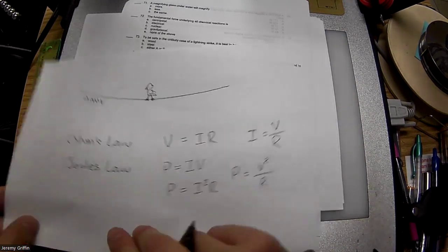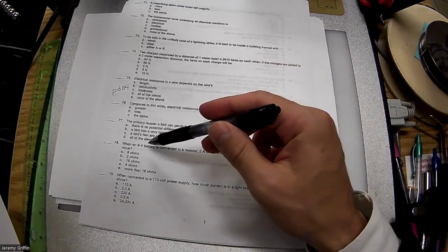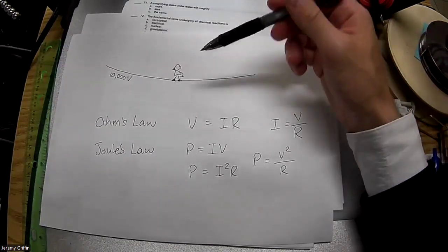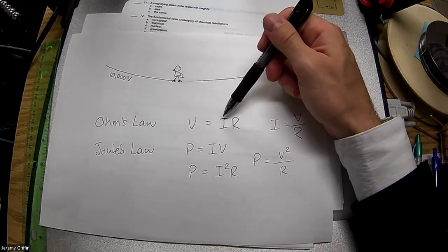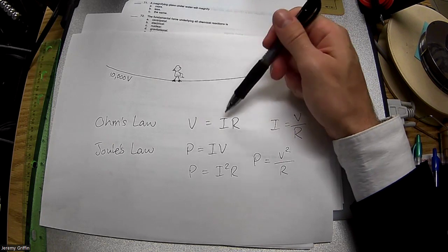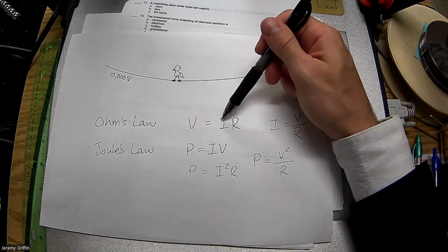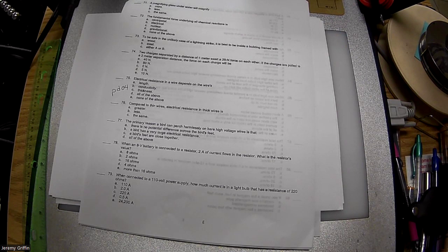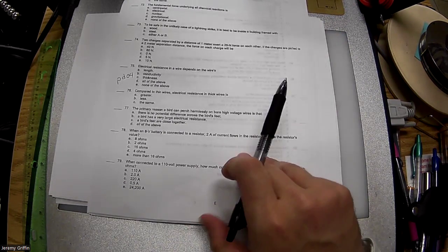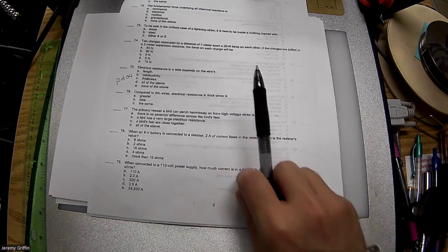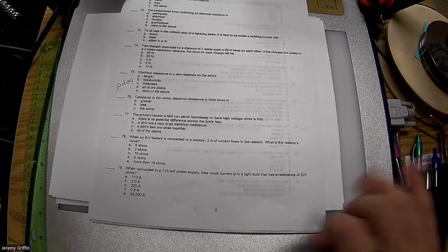So what's this question? 8 volts, 2 amps. What's the resistance? All right. So here I got 8 volts. Here's 2 amps. What's the resistance? You see it? Guys, what's 8 divided by 2? 4, right? Or if you like, 2 times 4 is 8. So I'm looking at 4 ohms. And of course, when you get this exam and all the numbers are changed, you can still apply Ohm's law, right? Because you just wrote down Ohm's law in your study guide, and so you'll have that.